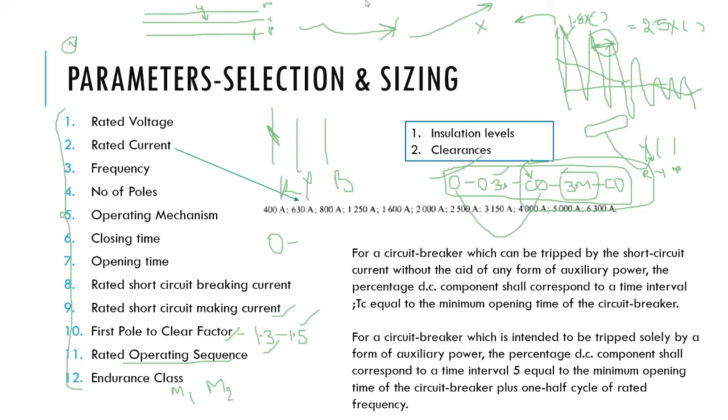For the auto reclosure, some conditions have to be satisfied, which I will talk about in the control and protection class. There should be a dead time, which is generally 0.3 seconds. After 0.3 seconds, I am forcefully closing the breaker with an assumption that the fault is transient. If my guess is right, well and good. The breaker closed again and the operation goes on.